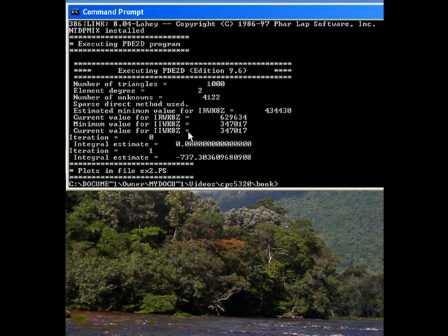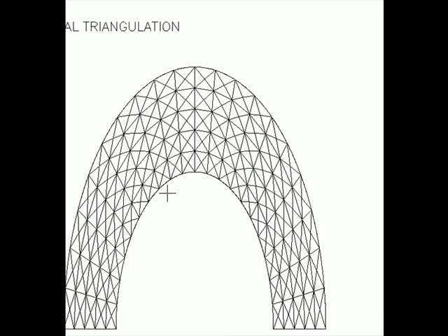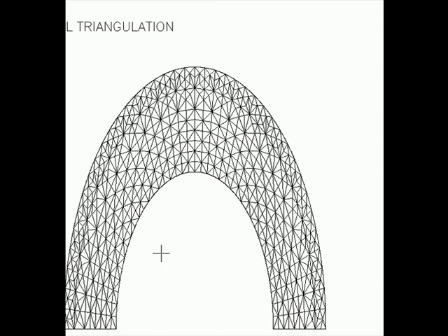Now let's look at the plots. There's the initial triangulation. Remember, we made a p and q grid, an r and theta grid, and in each grid square there are automatically generated 4 initial triangles. So this is the initial triangulation, but it was all generated automatically. And then there's the final triangulation. We said we wanted 1,000 triangles, so the 400 were divided.